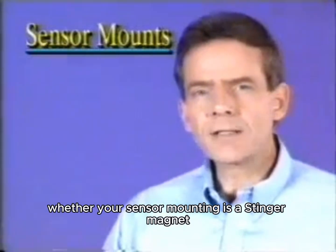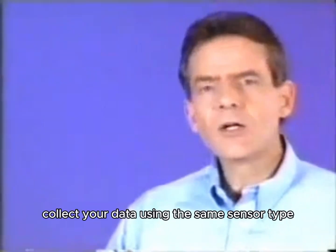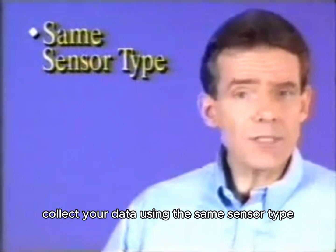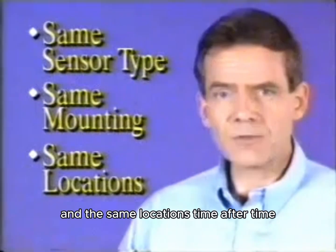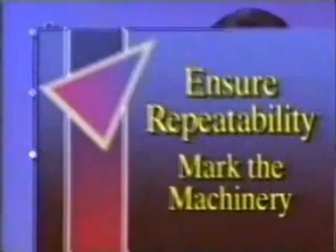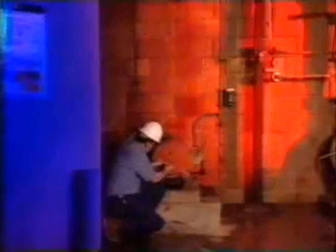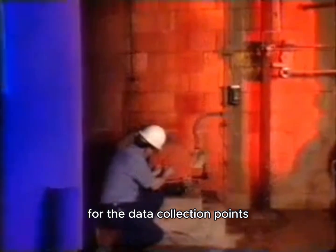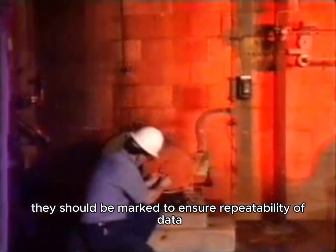Whether your sensor mounting is a Stinger, magnet, Quick Connect, or stud mount, collect your data using the same sensor type, the same sensor mounting, and the same locations time after time. When the locations have been selected for the data collection points, they should be marked to ensure repeatability of data.